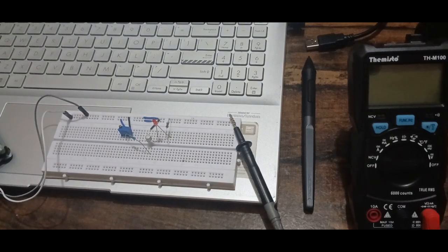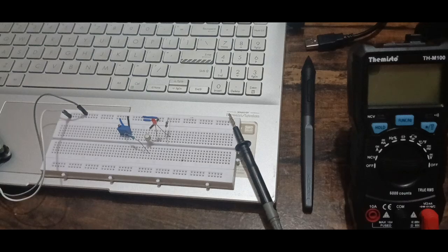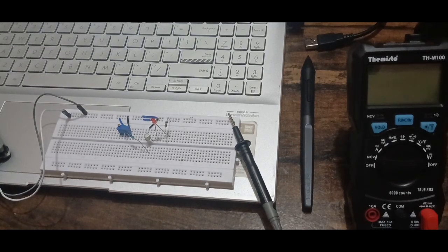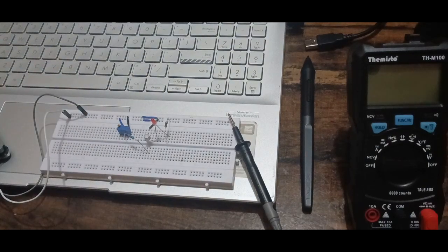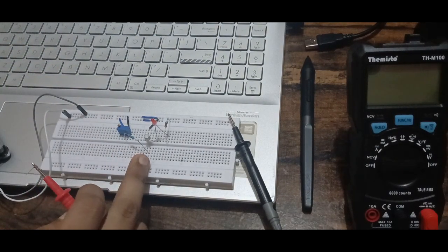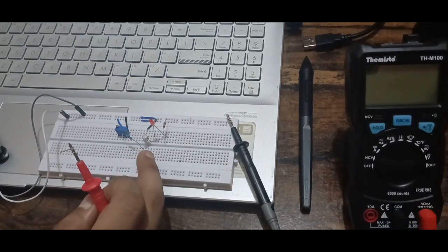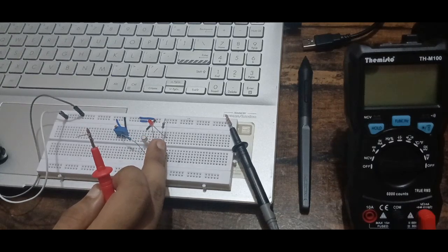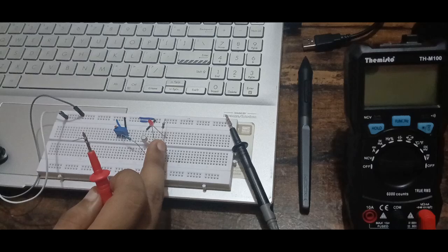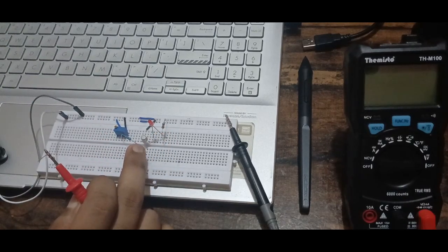So in part 2, which is our BJT driver circuit, our objective is to study the behavior of the BJT driver circuit for driving an LED and analyze its performance under varying input conditions. So I provide the 5 volt through this pot, and this resistor is connected to the base, which is our 10k resistor, and through the collector an LED is connected, in series with a resistor, which is our 220 ohm resistor, to the VCC, and our emitter is grounded.